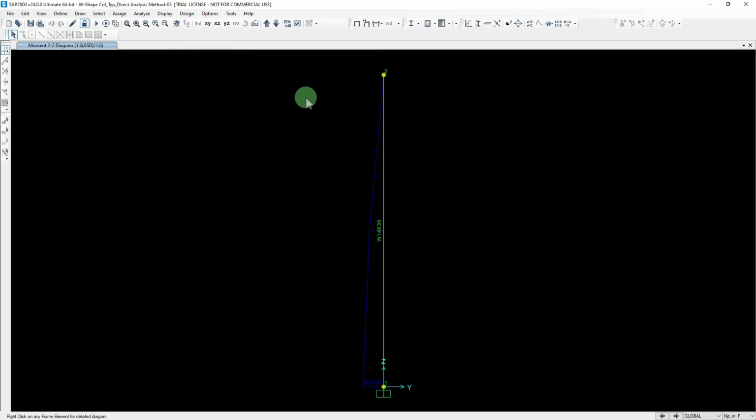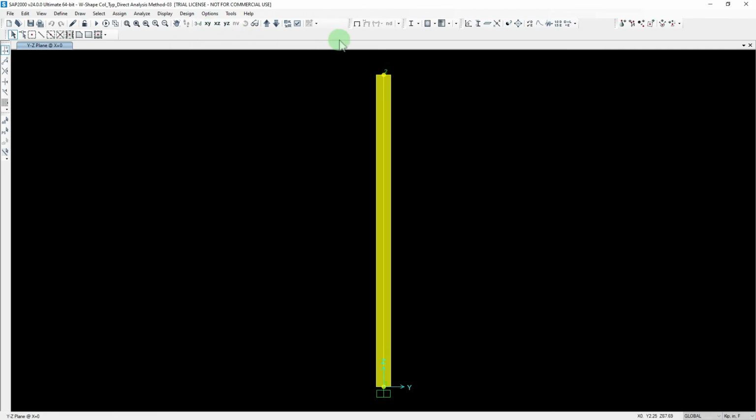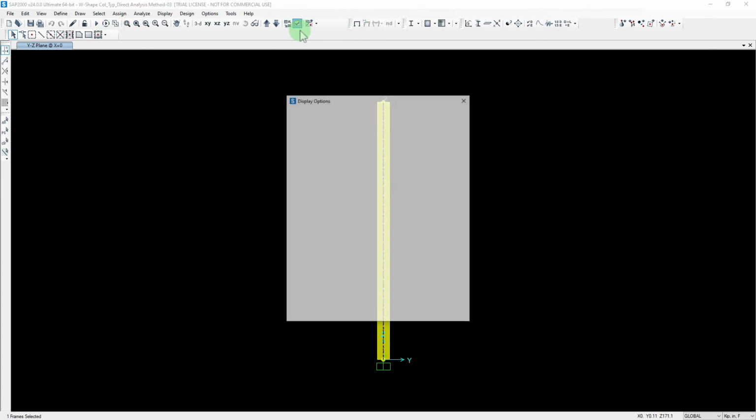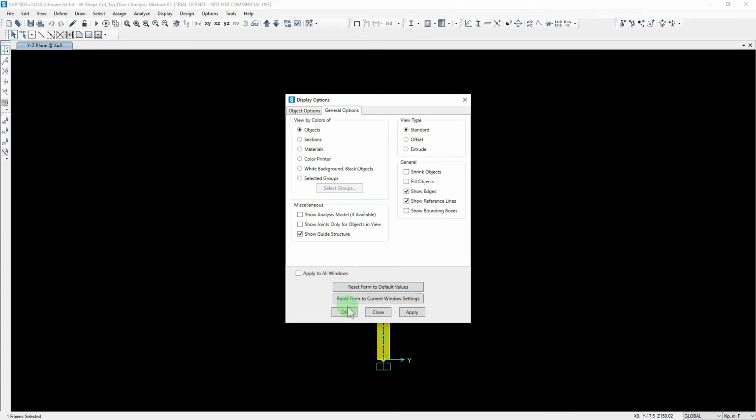Essentially, you might think, okay, now I'm good to go, 100%. In this case, I calibrated the structure to fail at that load. I want to demonstrate the effects of making modifications to the mesh. So I'll unlock this, and we'll see the effects of making modifications to the mesh setting. I'll do that by copying this over. Let me change the view for a quick second while I do that. Put it back in our standard view.